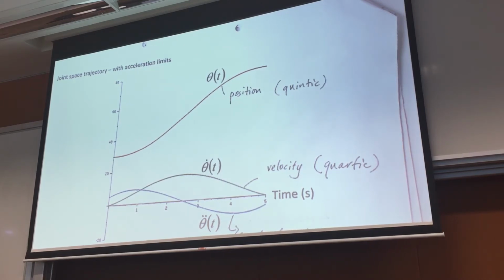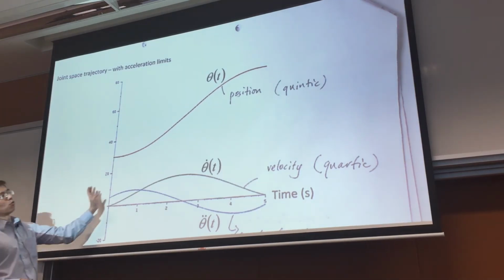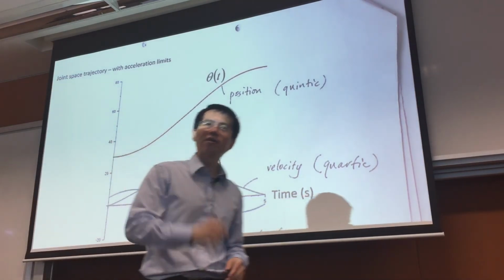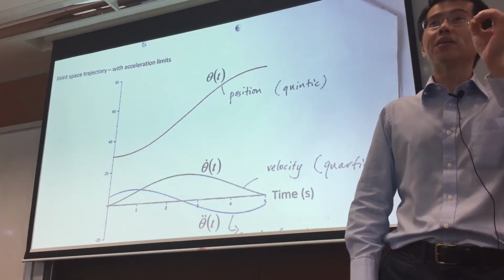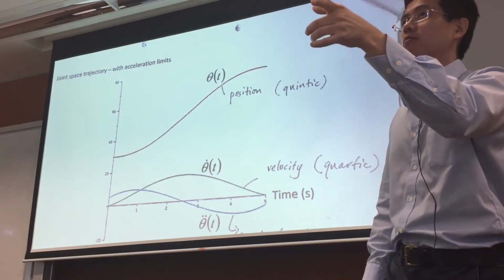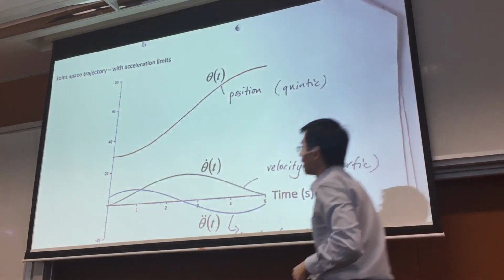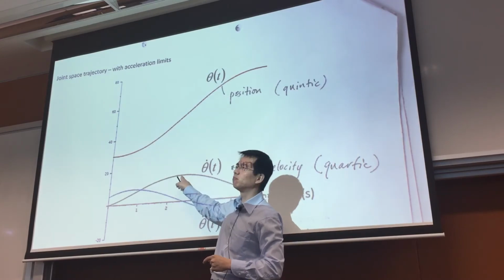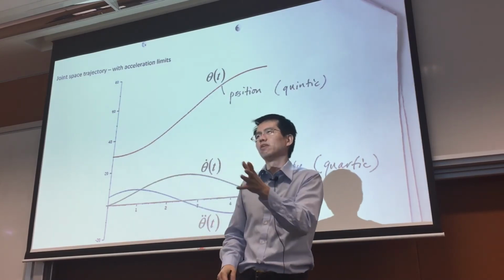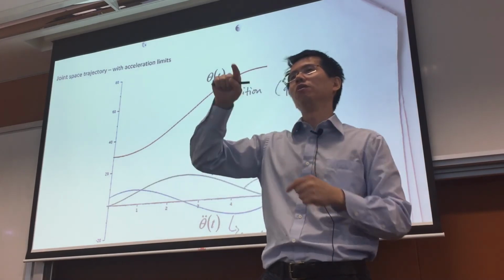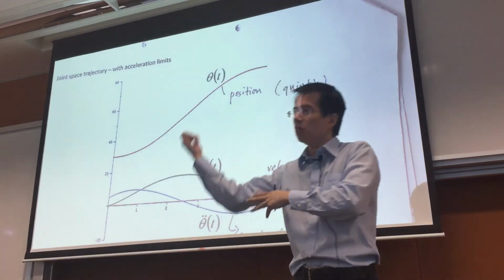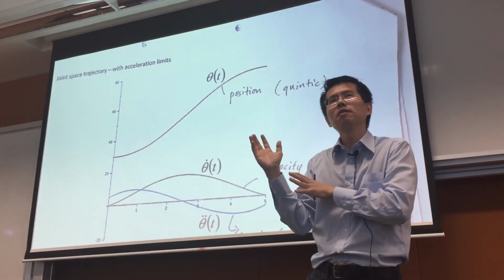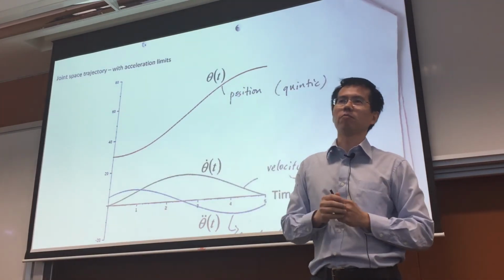And the other interesting feature is that as it goes through this acceleration profile, you'll notice that there's one point there that has acceleration as 0. What does acceleration 0 mean to you? Constant velocity. So at that point, you have a point that is considered a constant velocity, but there is also your maximum velocity. So if you want to find out, as your arm moves, what is that maximum velocity, it will be when acceleration is equal to 0.